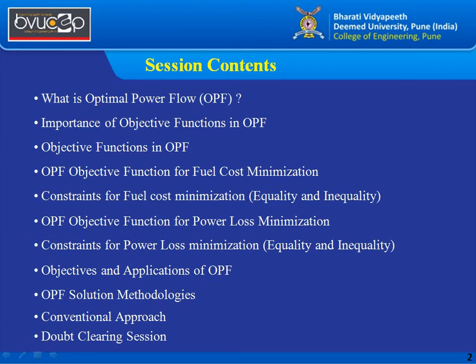The other difference is that for normal load flow studies, we consider only the steady state condition, which is the major drawback, because we cannot apply it for a normal power system, as you know the complexity of the power system is quite large, and it should have analysis in real time data.